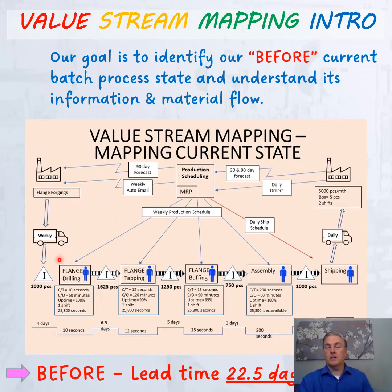But you can see in this operation down below, we've got our material flow here. So we're taking into consideration our cycle time, our changeover, our uptime, how many shifts we're scheduling, everything. And then we're looking at each of the individual operations. So we've got four operations here to make this part. It's going to a flange department where they're drilling, really a drilling department, and a tapping department. The flange is then going to a buffing department, then it's going to an assembly department.